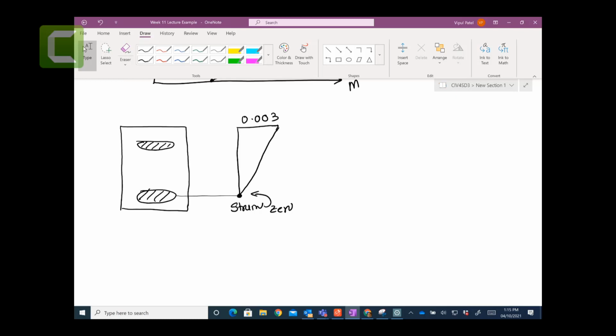So this is a strain, and you know the stress as well from our theory, that if this strain is 0, then stress is 0 here, right? So this is the stress profile, let's say. And then the concrete is not fully stressed, so this is a stress block. You remember from our beam example, gamma kud.